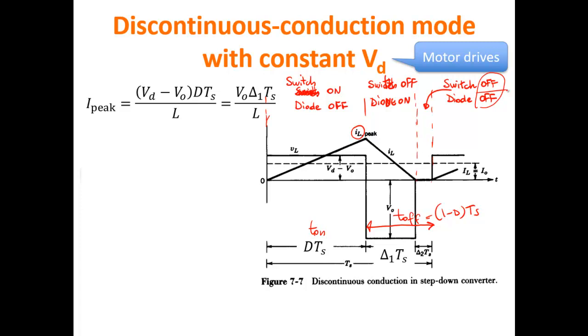This is, let's say, a phase of operation which is more and more important now, because actually, as I mentioned before, systems always go in standby mode in order to dissipate less power. So the current in the load can change rapidly by orders of magnitude and many times during one single day. So this type of operating mode is becoming more and more important.